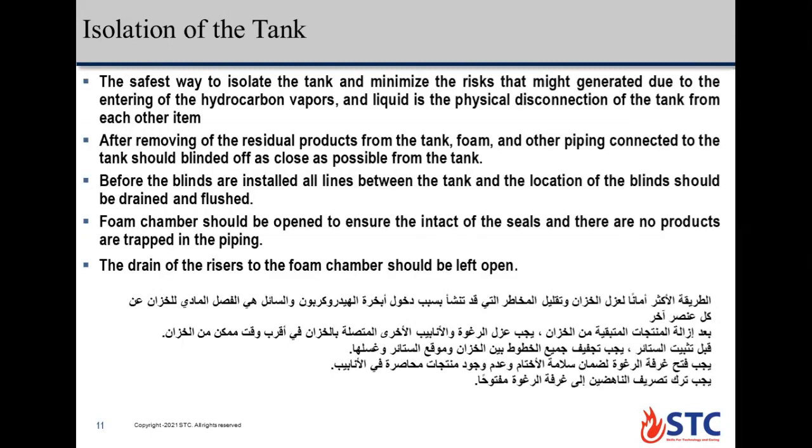Isolation of the tank. The safest way to isolate the tank and minimize the risk that may be generated due to the entering of the hydrocarbon vapors and liquid is the physical disconnection of the tank from each other item.